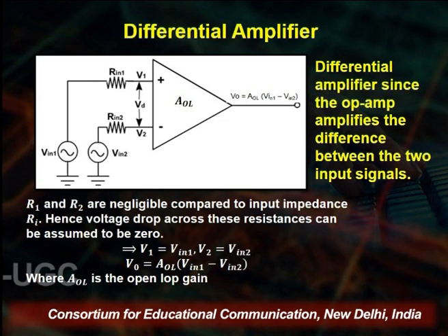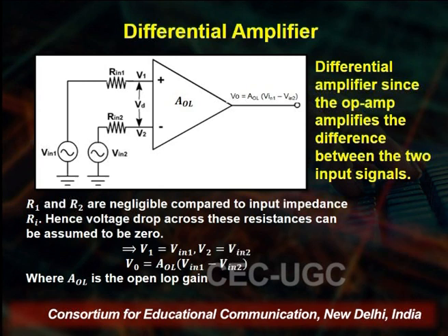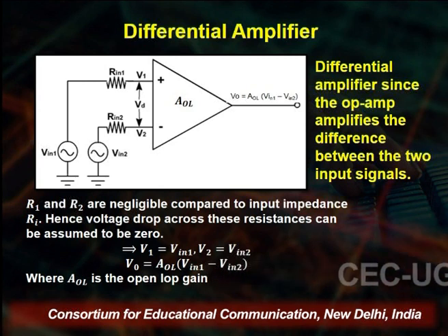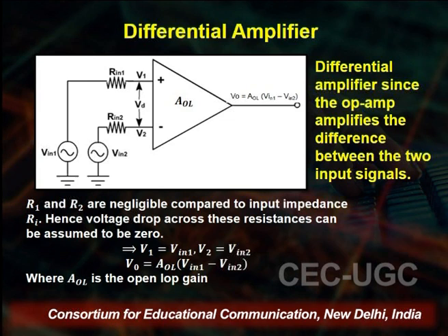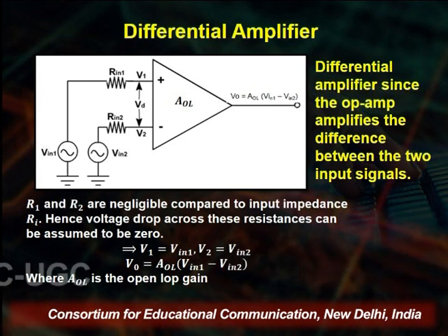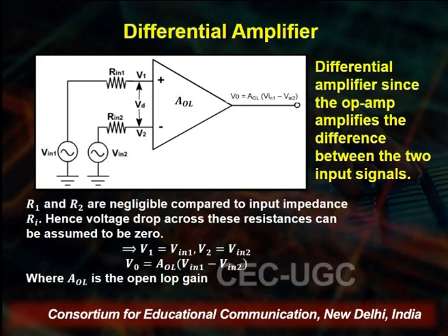As one can see from the figure, we have the input voltages at pin number 1, pin number 2 and pin number 3. In this case, we always affix a resistance, typically of the order of 330 ohms to about 1 kilo ohm, with pin number 2 and pin number 3, just to provide stability to the circuit.